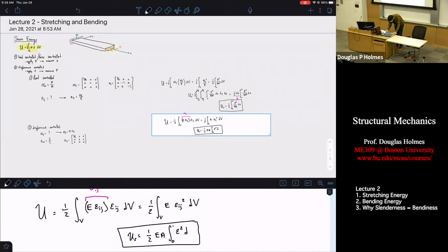Physics 1 freshman year, what you learn is the energy of a spring is 1/2 kx squared, right? And you can derive what the force is by taking the derivative of your energy with respect to length. And then you get that the force is equal to kx. Strain energy stored in a spring goes with the displacement squared. This is true here. Remember, your displacement is inside there. It's buried in the epsilon term. We're just normalizing it by length, talking about strains instead of displacements. But this is the same. It's Hooke's law, the same thing as you saw in freshman physics. The energy stored in a spring goes with the displacement squared, and all we've done is said it goes with the displacement squared relative to its original length.